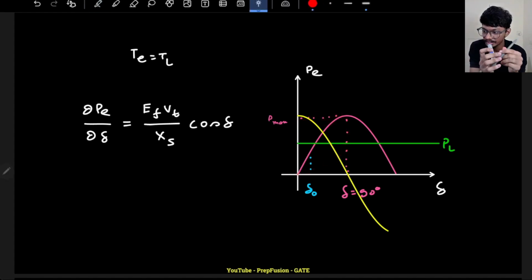So suddenly if I apply a heavy load on the rotor, what will happen? The MMF of the stator side will still rotate with speed ns, but if I apply a heavy load, it will not stop, but for a second it will jerk, and that delta angle will increase, correct? So what I am telling is this is freely rotating. If this is freely rotating, suddenly if I have an opposition here, it will not freely rotate. It will rotate, but still with a certain jerk, right?